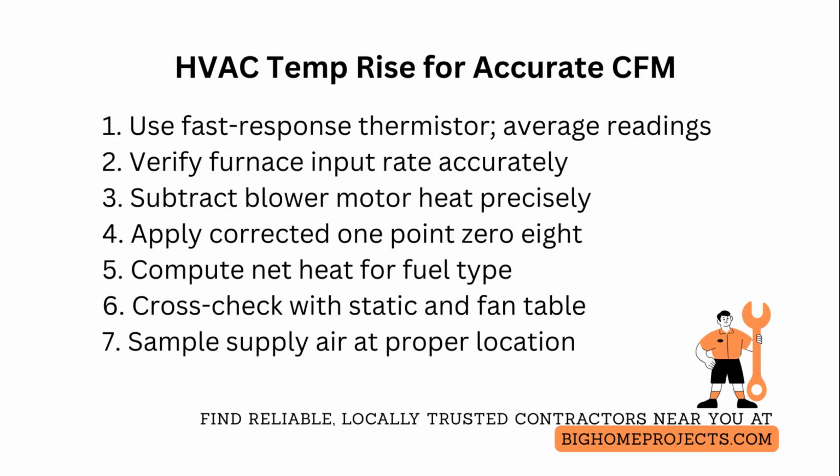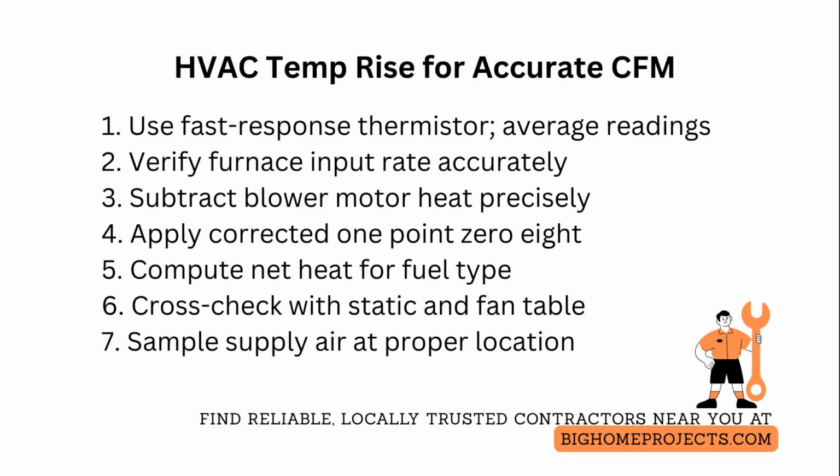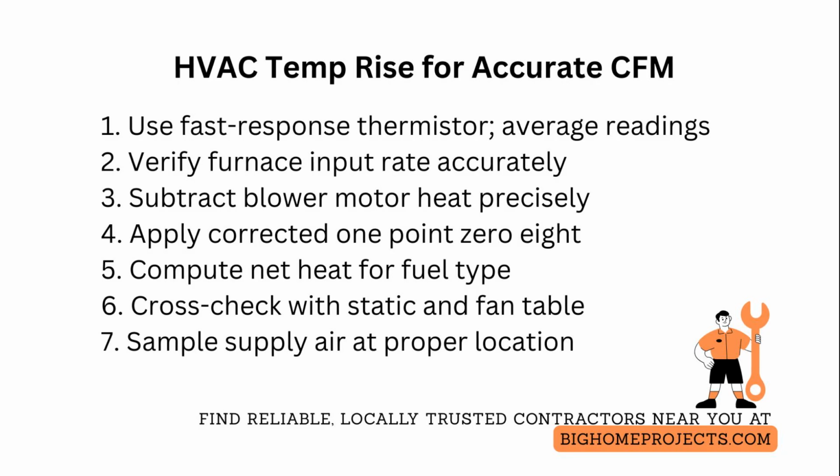Confirm the furnace input rate with a clocked gas meter or nameplate electric heat kilowatts, then subtract blower motor heat using measured voltage, amperage, and power factor to derive true net heat to air.